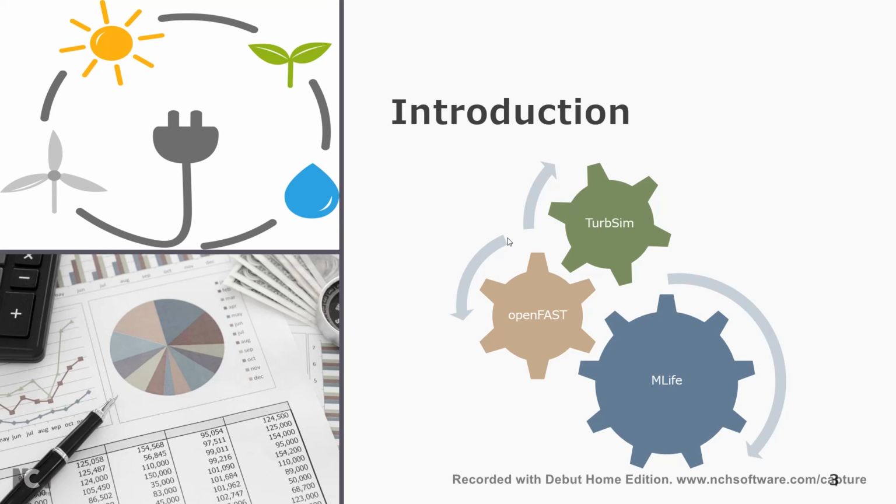Wind velocity in X, Y, and Z direction, the forces in the X and Y direction, the moments in X and Y directions, the max loading, the tip deflection, in plane, out of plane tip deflection, tons of different things. And you use MATLAB or another program called PyDatView, a Python library, to view those results.